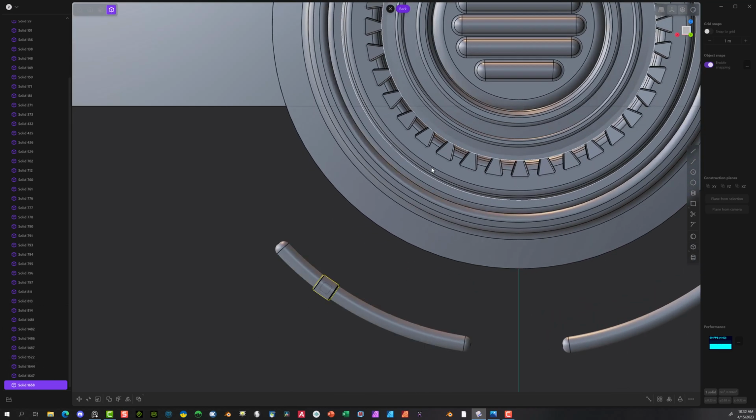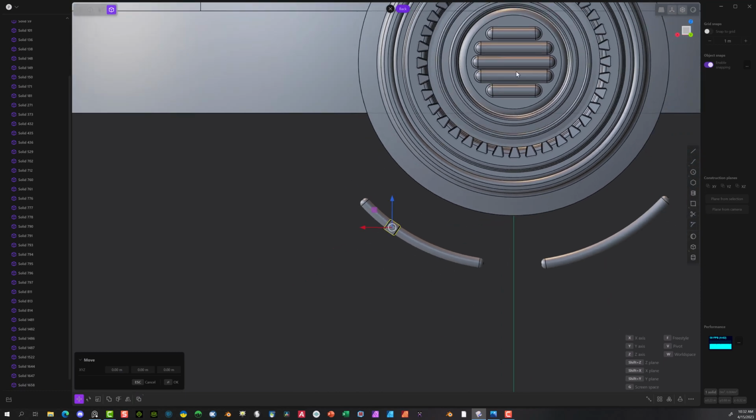And we're going to do a Shift D. I'm going to do a V. And we're going to go right to the axis here. We're going to rotate with R, V, Control Z. I'm going to do R again, V, and we're going to make sure we select this blue. Something like that. Cool.